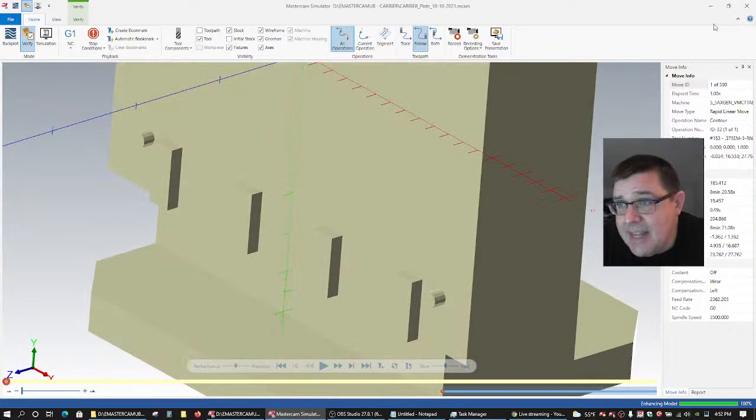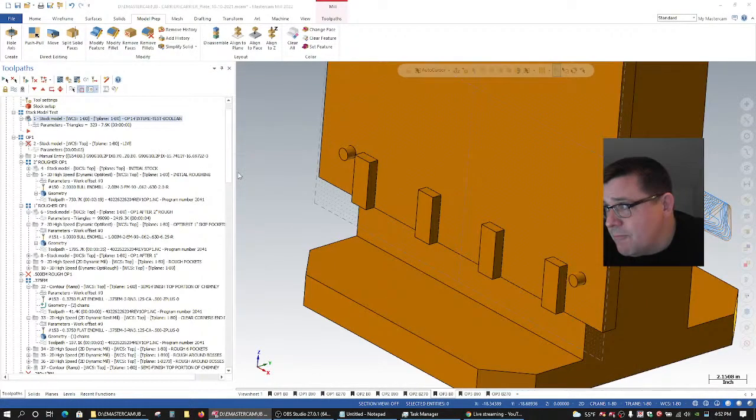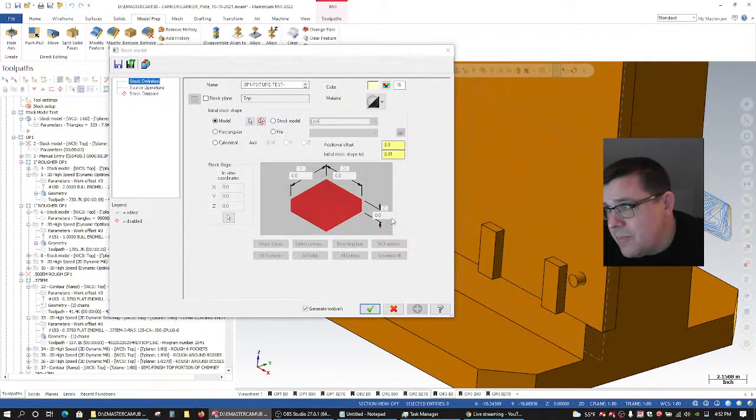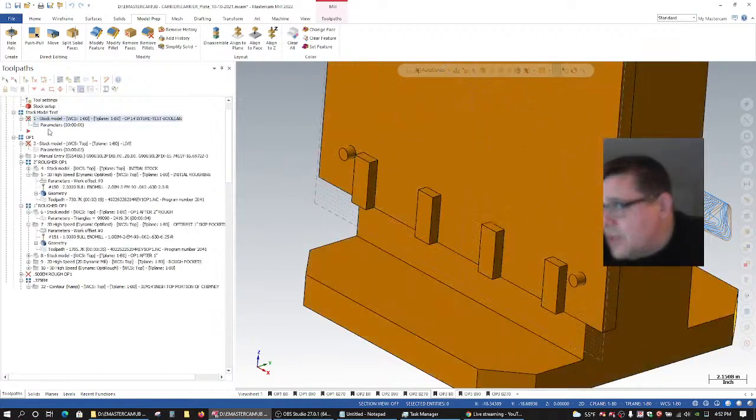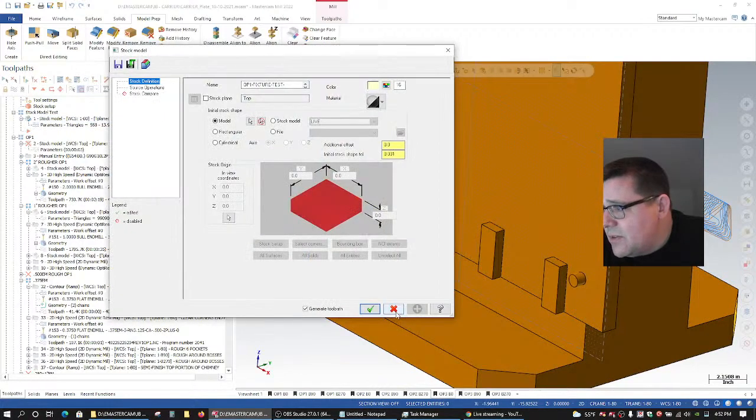But here's a 10 thou stock tolerance. And if I make this, let's make it 4/10. 1 thou is the limit, all right? So 1 thou, 0.001. It's going to regen. And it's 568 triangles.